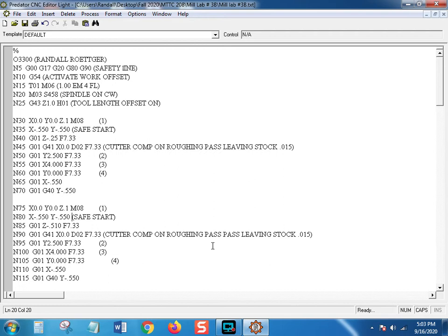Well, the biggest reason is you can't see it, but the control can. So the control will go down and it'll say there's an error here, and it may tell you what line or it may not. Chances are it won't. And you'll look and you'll say, well, there's nothing wrong with that. Guess what? You got ghost code in there. And it's real easy to do. Sometimes all you got to do is accidentally hit one key and you don't even see it. I know that sounds like bull, but trust me, I've taught this stuff for many, many years. We've had students with perfectly fine looking files, and I'll say, it's probably got ghost code. We stick it in another editor and it shows all this stuff we never knew was there. That's why we call it ghost, because you can't see it when you first write it. So beware of ghost code. It actually exists.